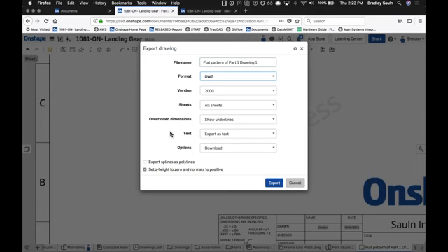One of them is going to be using splines instead of polylines on the import. So this will be very important for laser engraving or just laser cutting in general, to make sure you get those nice smooth lines instead of those small, multiple straight lines connecting to make up that curve.